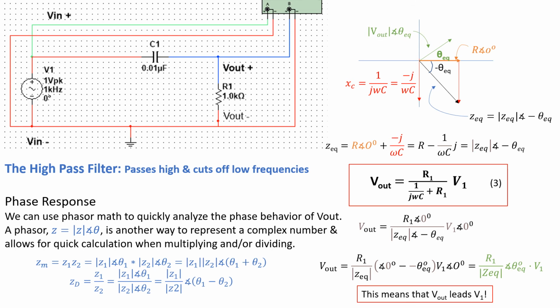Now, let's back up a second and explain why complex numbers appear in the first place. First, j is used in circuit engineering because I, little I, typically represents current, so a new variable was found. Furthermore, complex notation appears because sinusoidal voltages do not combine mathematically like real numbers. Mathematically, they combine like vectors, and this is why complex numbers are used.